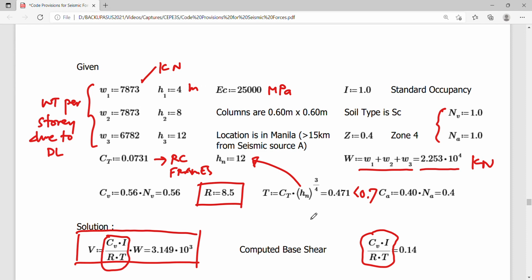Okay, so when you say high frequency, your f is actually greater than more or less 1.0. And if it is less than 1.0, this is a low frequency building. This is a high frequency building. So this 0.7 seconds is actually lower than 1.0, but still this is the basis for determining when to consider the whipping effect.